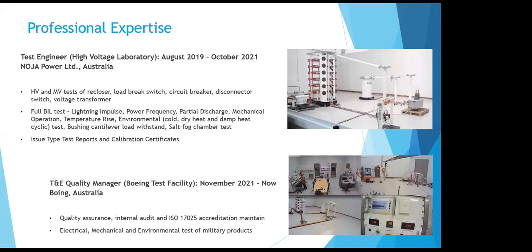In Noja Power's high voltage laboratory, I got experience of conducting full basic insulation tests like lightning impulse, power frequency, partial discharge, different types of environmental and mechanical operation tests, different types of temperature rise test, bushing cantilever withstand, salt box chamber, this type of test. After conducting these tests as per corresponding IEC, IEEE, and Russian standards, it was also my responsibility to prepare the type test reports and calibration certificates.